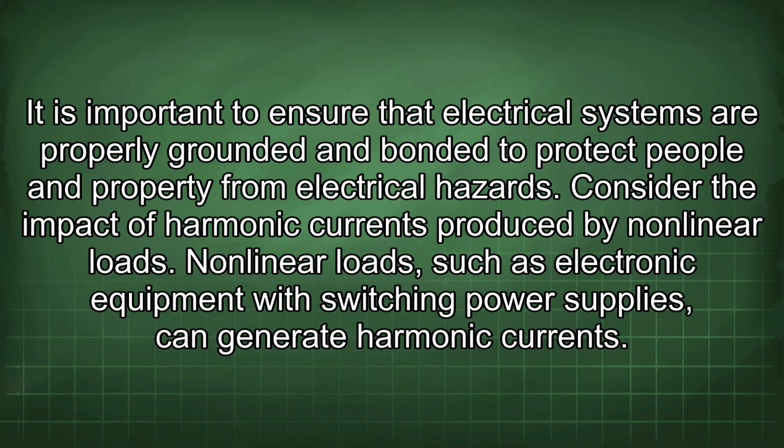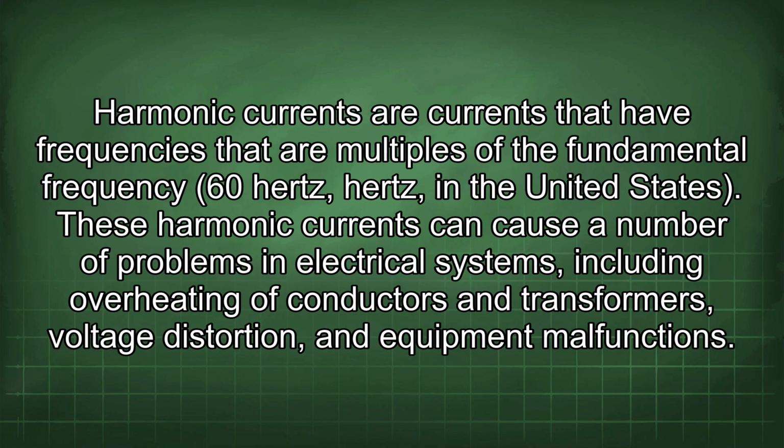Consider the impact of harmonic currents produced by nonlinear loads. Nonlinear loads, such as electronic equipment with switching power supplies, can generate harmonic currents. Harmonic currents are currents that have frequencies that are multiples of the fundamental frequency, 60 Hz in the United States.